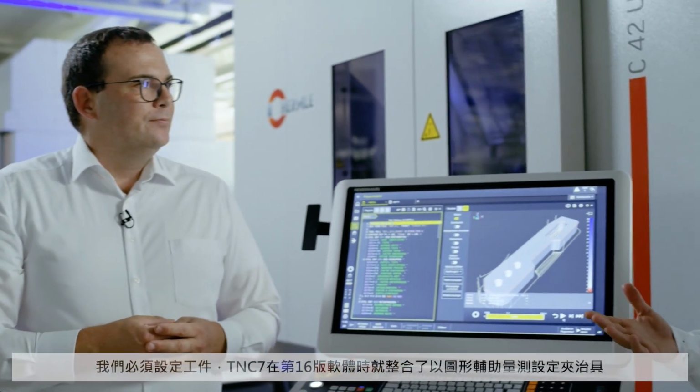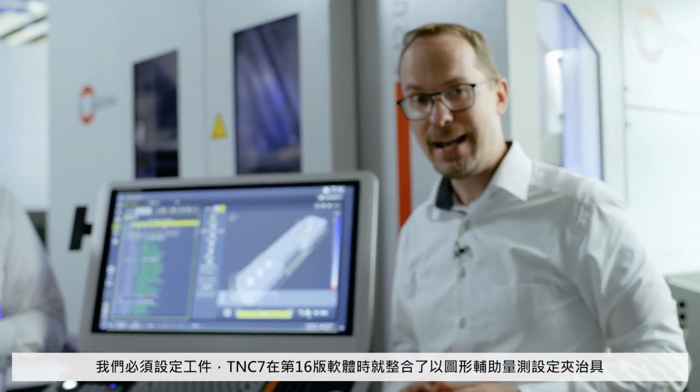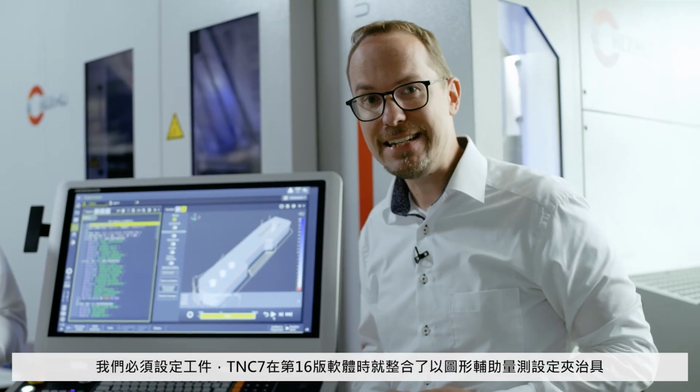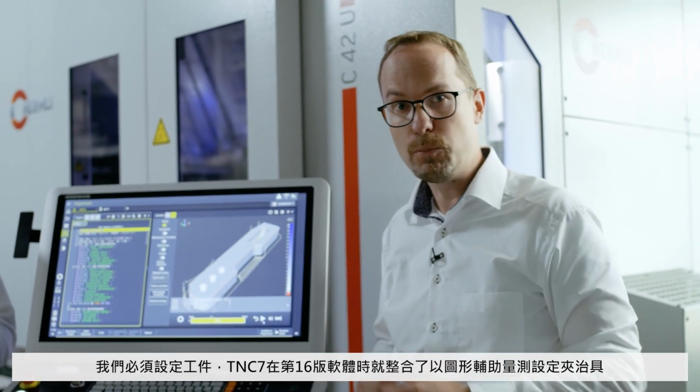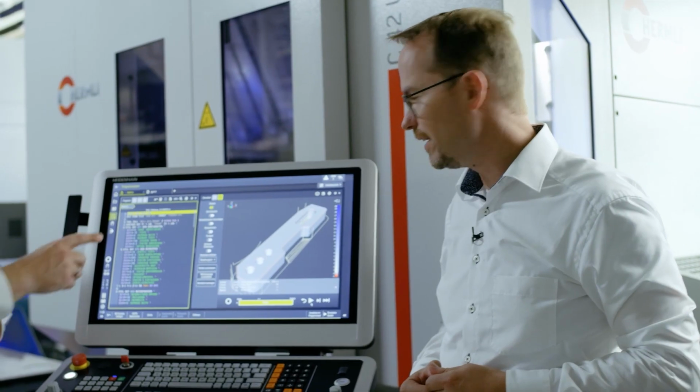But one last step is missing before we can begin machining. Martin? Right, we have to set it up. Software version 16 was the first one for the TNC7. There we integrated graphical measurement and setup of work-holding equipment like vices. With version 17, we've gone one step further. A very important additional feature is graphical measurement of workpieces themselves. Here's a brief example of how that works.